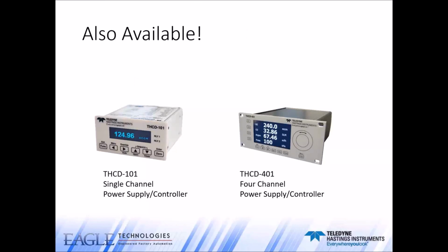And we're also proud to announce the release of our latest certified drivers. Eagle Technologies has produced certified LabVIEW drivers for our single-channel THCD 101 power supply controller. So the 101 can provide 24-volt or plus minus 15-volt to power flow meters, flow controllers, vacuum gauges, or various other sensors. The single-channel THCD 101 accepts linear analog signals and will display readings with units on its bright display.